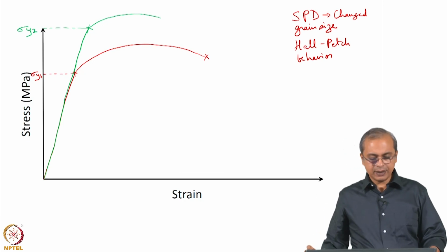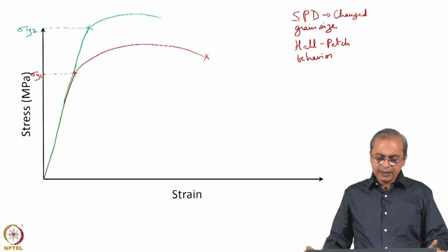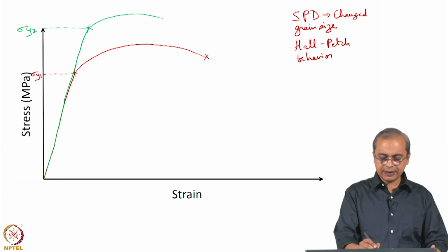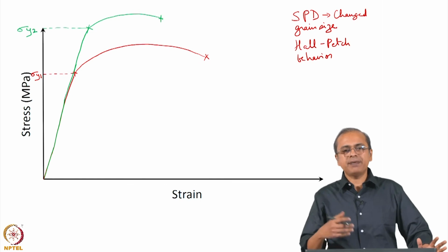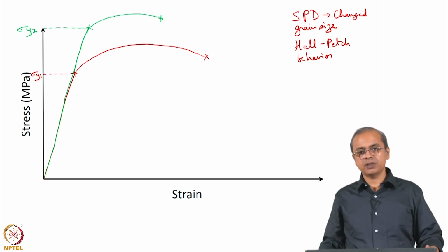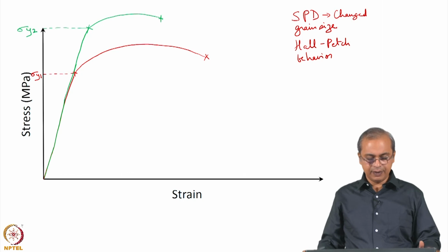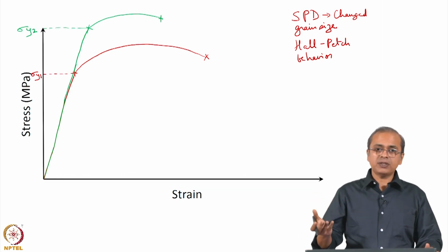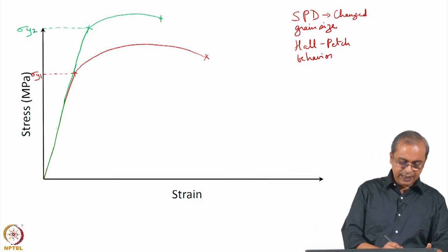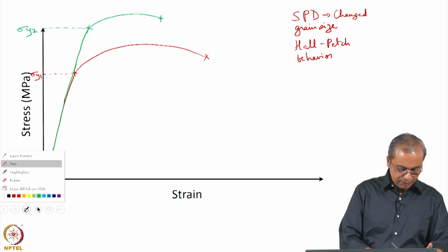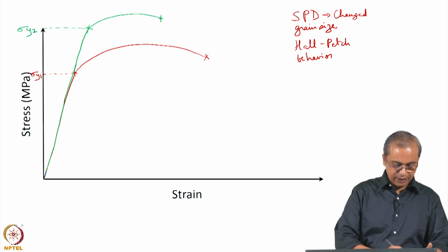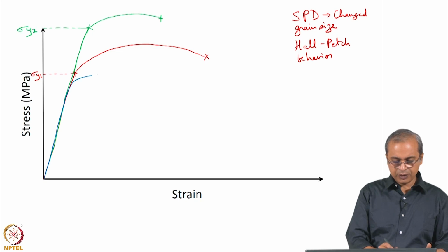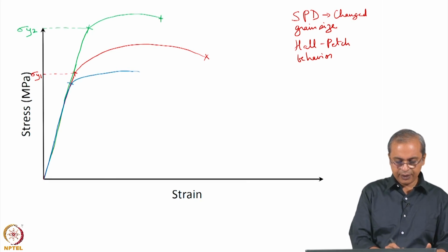Okay, and so that is how the strength will change, and the amount of plastic deformation that it may undergo before failure may change. It may not necessarily be the same. Usually when the strength goes up to some degree, the ductility comes down. These things are not absolute, but this is the general trend that you tend to see. In case the inverse Hall-Petch relationship is in vogue, you may see that it actually deviates from linearity sooner. So, you may see a behavior that begins to look like that. So, you may have a lower sigma y.